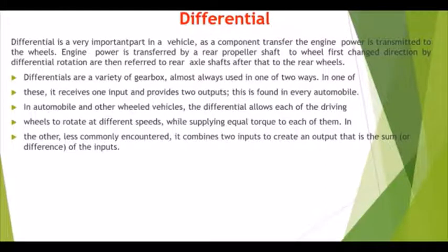In that case, if you go with the four-wheel drive, the torque which is transmitted will be equally distributed, and all four wheels will rotate on their own motion. So if you travel in skiddy areas, mud or water, anywhere, you will be in a position to run your vehicle. So that is a major difference.